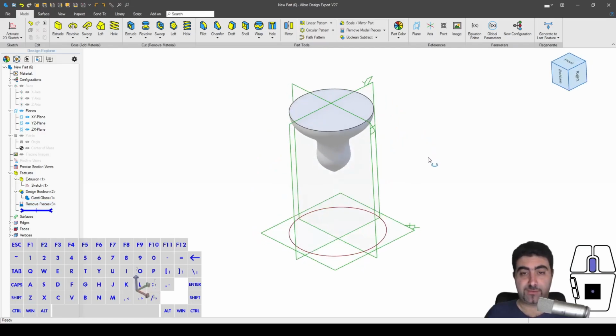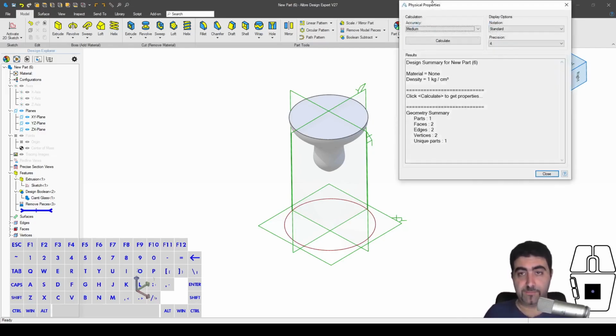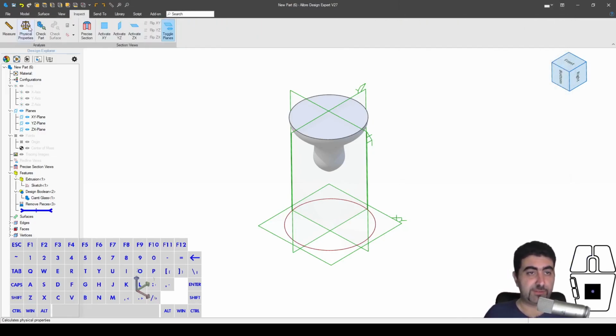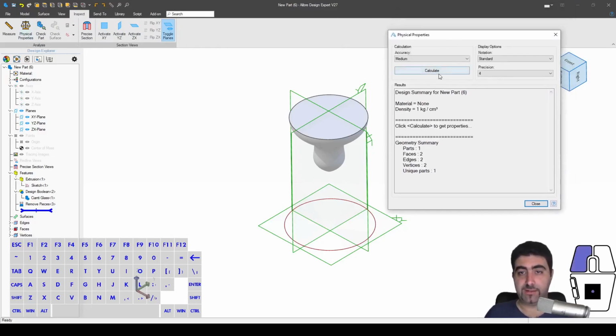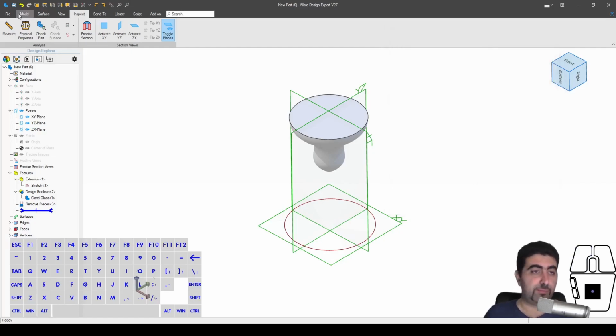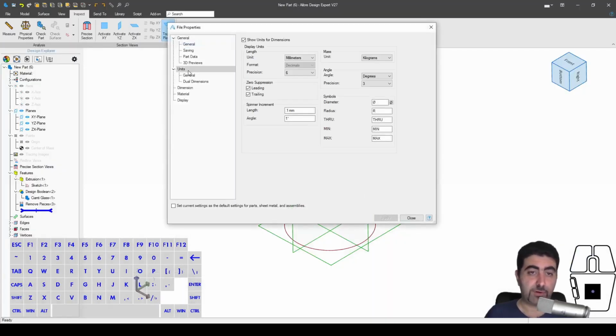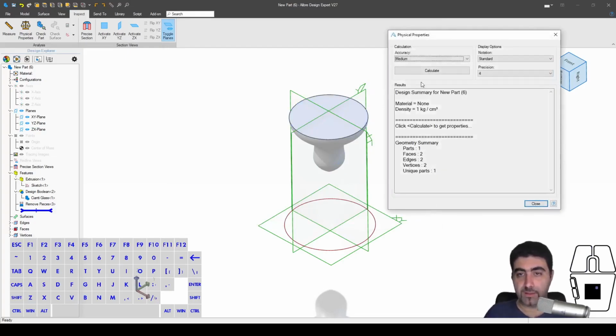And look what I have now, right? This is the volume of fluid inside that glass, and I can just go to my physical properties, inspect physical properties. I've hotkeyed that, calculate. Guys, this is your volume precisely, right? If you want that in ml or cubic centimeters, you just change your units to centimeters. Calculate again.